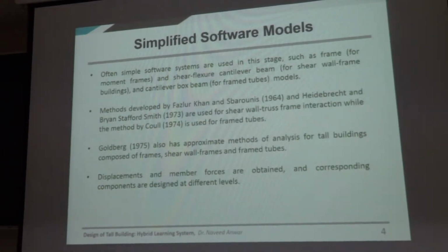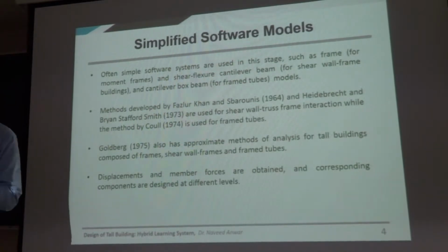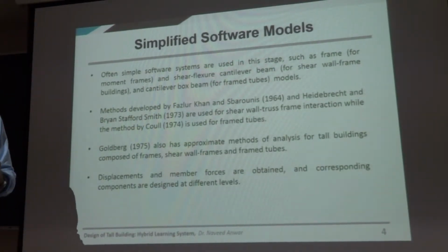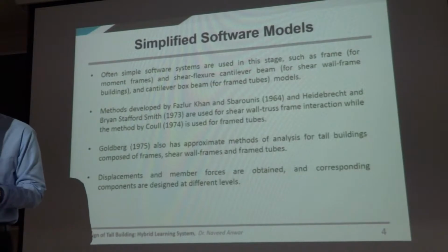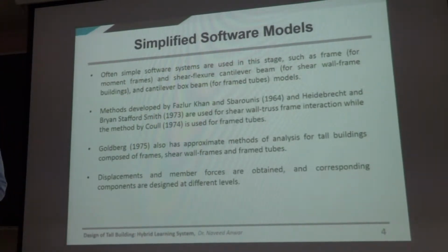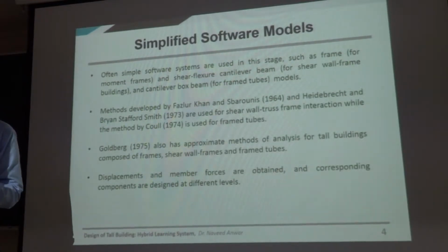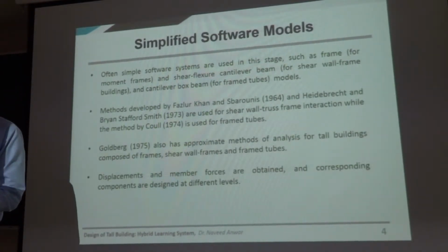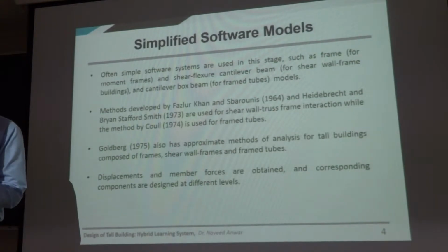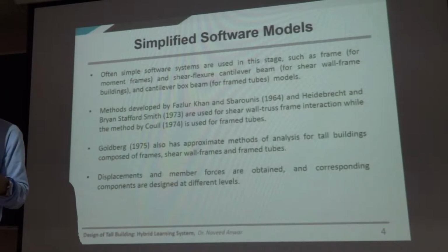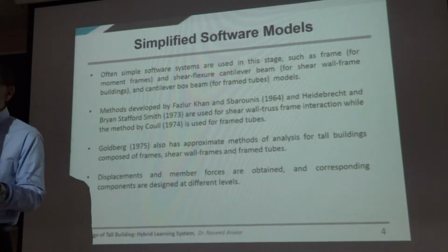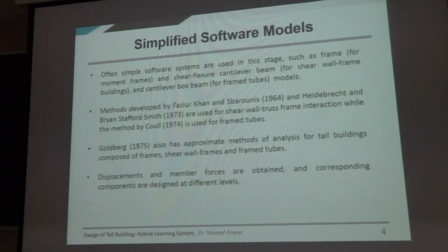Are we going to use flat slab? Are we going to use beam slab? Are we going to use a steel structure there? What is going to be the floor system? And floor system does not really depend too much on the number of stories, because it's going to be the same, repeated everywhere. So that decision can be made almost independently of the height of the building or number of floors. It only depends on the planned sizes and planned layout of the building.